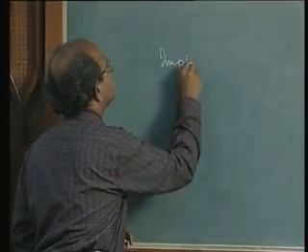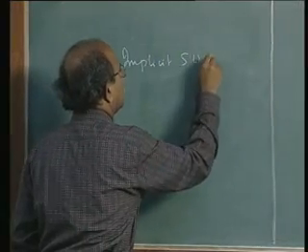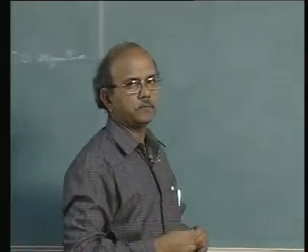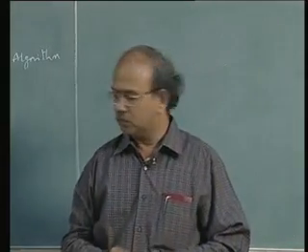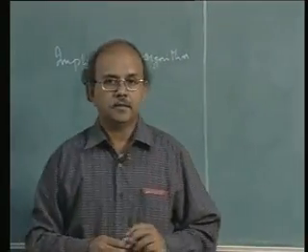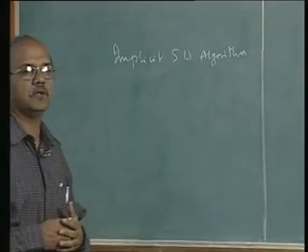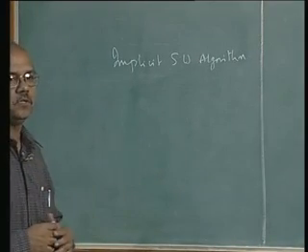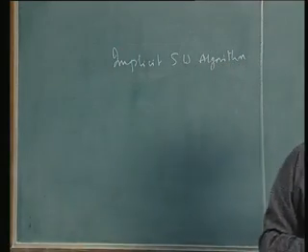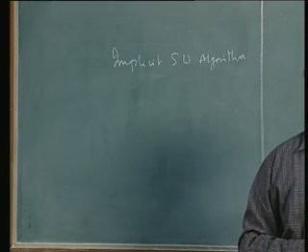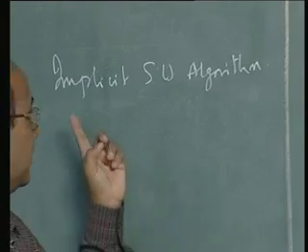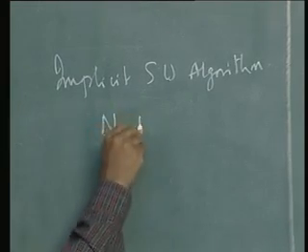What is called as the implicit stress update algorithm. We'll quickly finish this and go over to a different topic altogether, that is on what's called continuum mechanics and its fundamentals. As the term indicates, implicit algorithm, what we essentially do is to solve for both the stress state, that is, in other words, where the stress should ultimately fall, as well as the way we are going to update the yield surface.